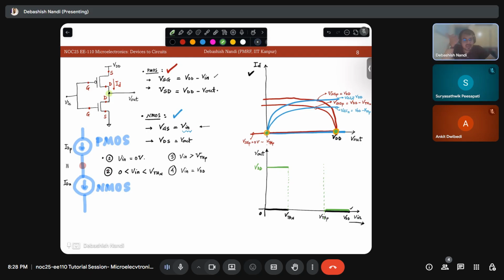So earlier you understood that NMOS part, right? 0 to VTHN. Yes, sir. Now you assume that you are starting at this point and going this way. So when you are at VDD, what is your VSG? VSG is 0, right? Or V in is VDD. So if VSG is 0, that means your PMOS is in cutoff. Cutoff. So that is why your current will be 0.